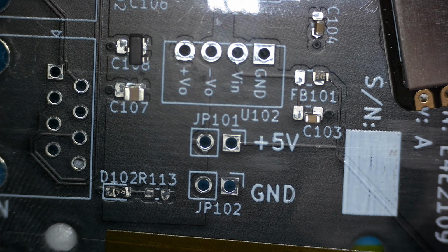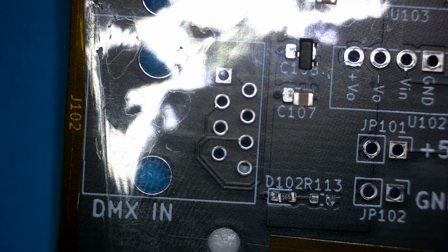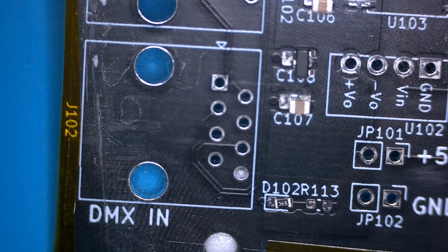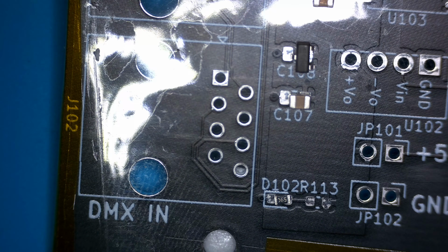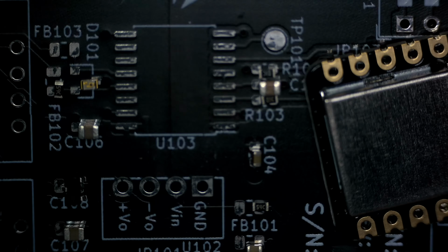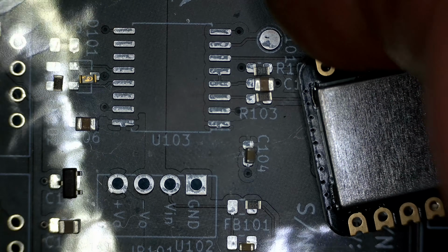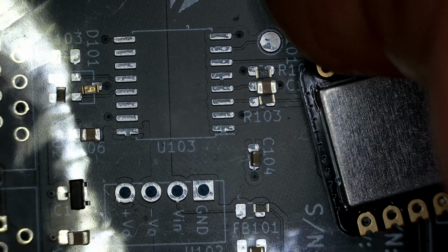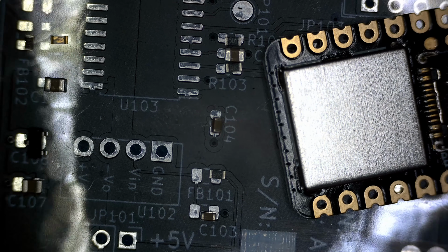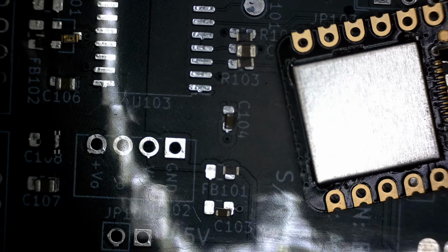I made a pretty simple mistake. It is pretty evident that some of these parts are not in the right spot, and there are some pretty obviously incorrect parts placed. Well, turns out when I was pasting into my CSV, I was apparently rushing, and in that hurry, I pasted the formulas, not the values, into the CSV. Yeah, it didn't work so well. So we mixed up all of the feeders and the coordinates, and it put parts all over the place. So let's try this again.